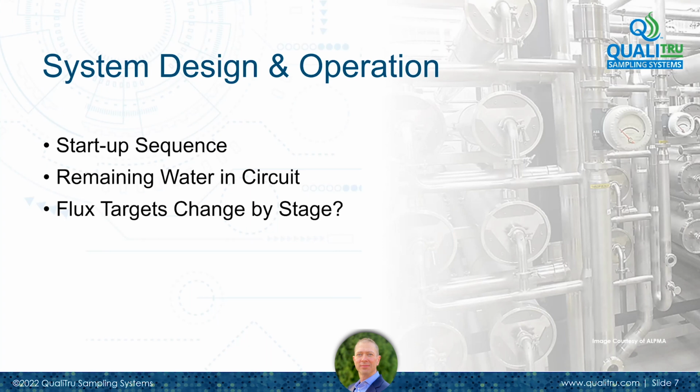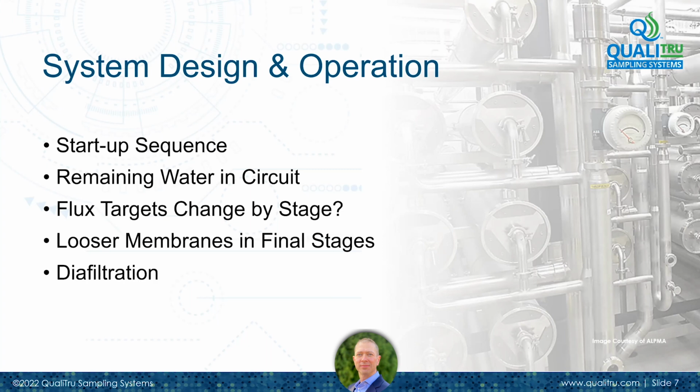Knowing what to expect in each stage is important to balancing filtration system health. Adjustments to target flux or stage pressures will allow every stage to complement the other ones and reduce overloaded stages that could die out early and reduce your capacity. Other considerations are potentially changing to larger pore sizes in your latter stages where there's thicker product, most likely. Adding back cow water, RO permeate as diafiltration techniques can definitely be helpful, or balancing systems with recycle streams.